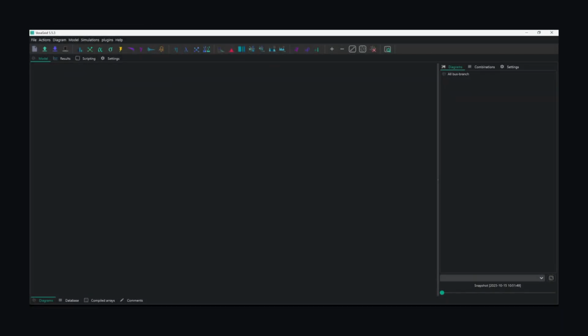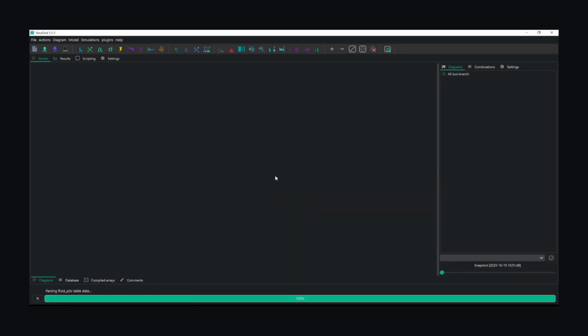Let us see now how everything we've discussed applies in practice. The first step we have is to set up the grid model. In VeraGrid, there are three main ways to do this. If you already have a network built in another software or exported in one of the standard interchange formats, you can simply drag and drop the grid file directly into the model.